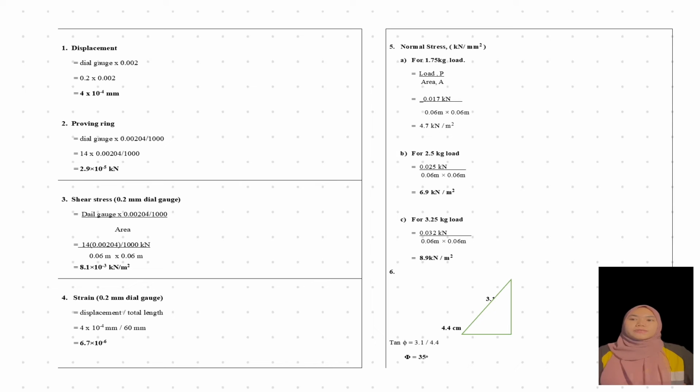Last but not least, the friction between sand particles is due to sliding and rolling friction and interlocking action. The ultimate values of shear parameter for both loose sand and dense sand approximately attain the same value. So, if the angle of friction value is calculated at the ultimate stage, slight disturbance in density during sampling and preparation of test specimens will not have much effect.